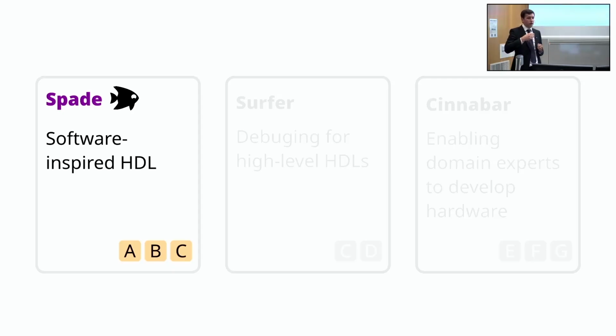And so you can't simply take a software programming language and apply it in hardware, at least not without much better high-level synthesis tools than we have today. So we need dedicated hardware description languages that allow you to reason about the things that we care about in hardware, but that are better than what we have now, and that's the idea with Spade. So if the motivation is software has a whole bunch of ideas, let's take them, but we also can't take them outright, what can we do?